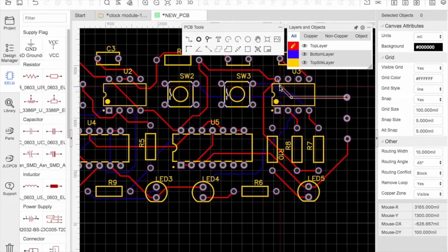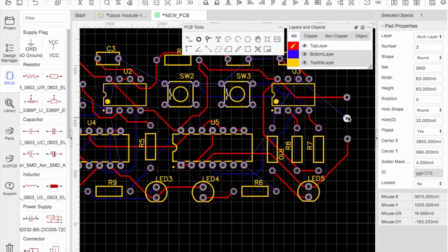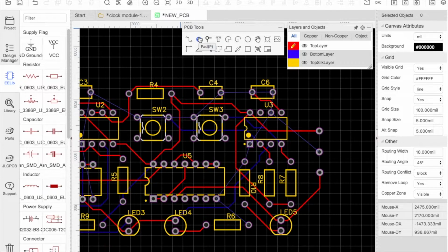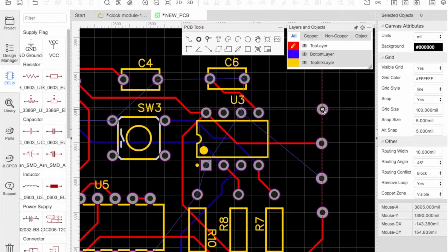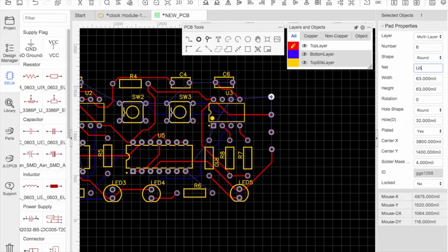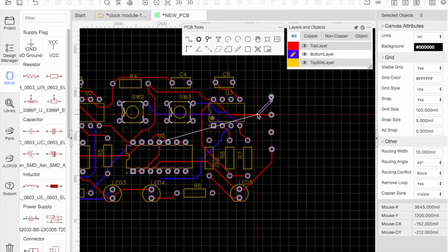I'll connect VCC to just one of the powers because they're all connected now, and ground can stay like that for the moment. And one last output that I'm going to need for purposes much later on in the build is an inverted output. That's going to be easy to do because we have an inverted output here. This isn't what the output should be, but then it's being inverted, and now this is a real output. So if we just use this as the inverted output, that'll work. And now connect it up.